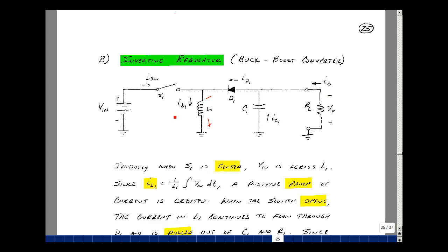We'll close the switch again, force a voltage across here that's equal to Vn. But now the voltage across here is some positive value, or this node voltage is negative. This one minus this one would make the voltage across here strictly negative. Again, the diode's off. We charge up the inductor, open the switch, polarity flips, because we're now discharging the inductor.